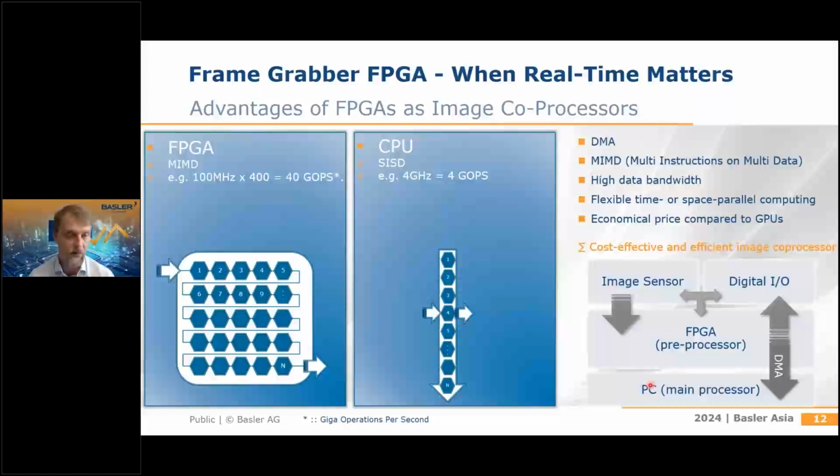So all of these DMA transfers will happen. And before the DMA transfer, or during the DMA transfer, you will have the FPGA working on the data. So during the acquisition, we can also perform pre-processing tasks, and the results are given to the CPU, and the CPU until then has not seen any work. So the CPU load is drastically reduced in this time.